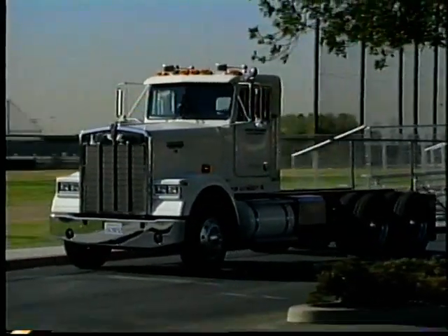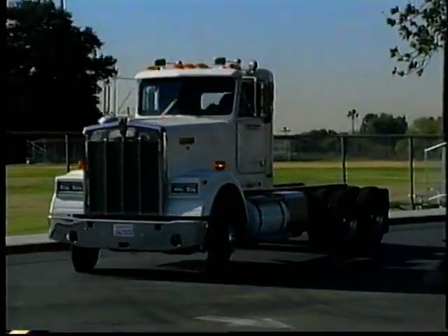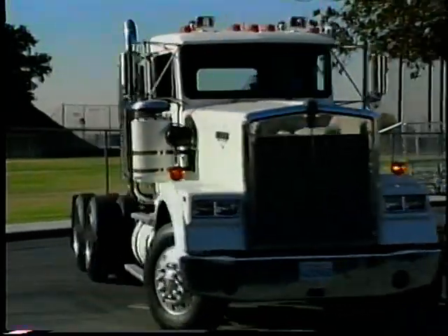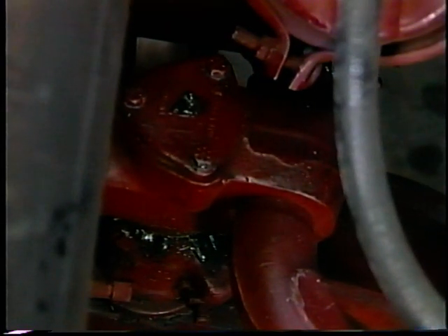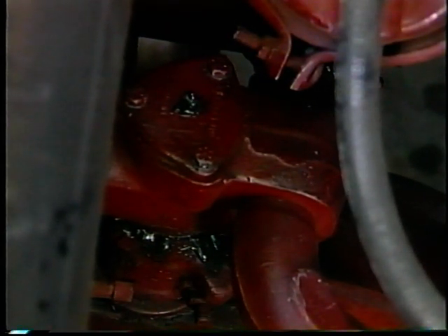KPI should always be checked for concerns about hard steering or poor steering wheel return, as well as for concerns with directional stability. KPI, like camber, is not adjustable and will require further inspection of the axle and the kingpins if excessive tire wear is present.